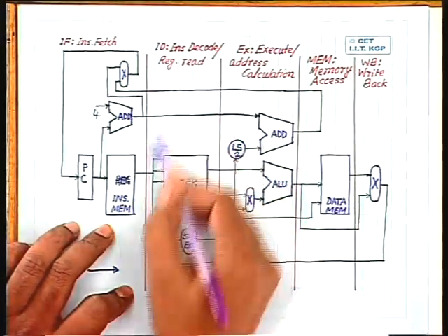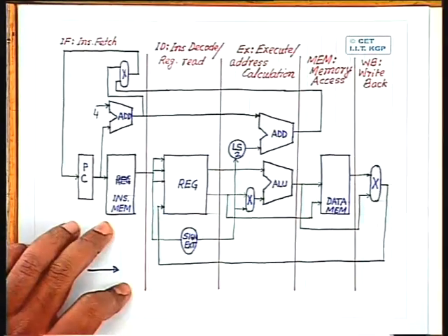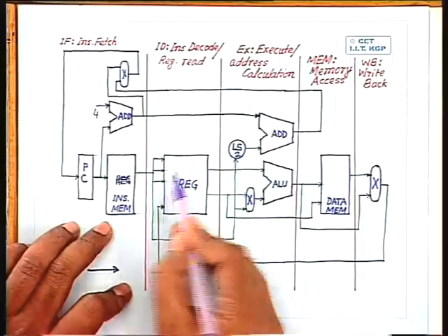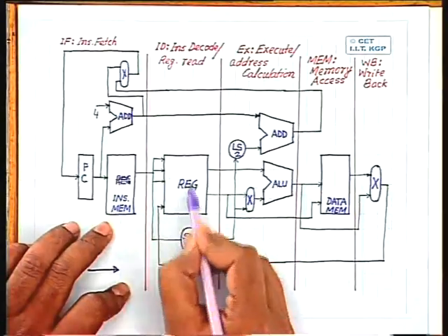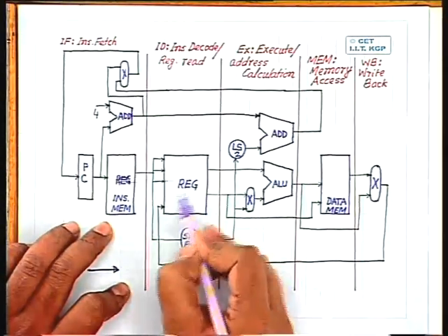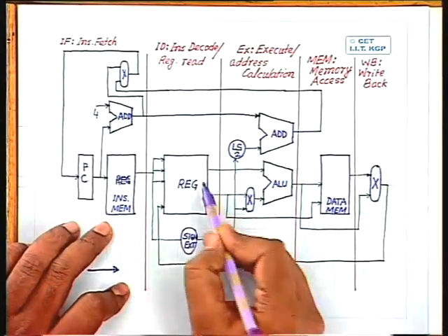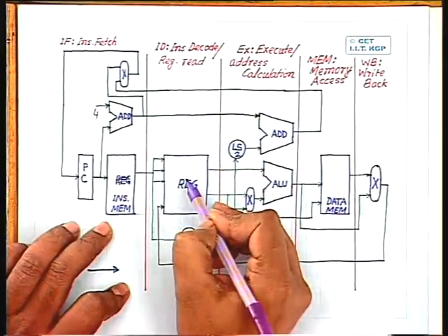In this particular case, possibly it will not lead to any problem, because the operation that you are doing in ID is only register read, and we have already said that even if you read the registers, you are not executing on them, you are not doing any performance on them. So the operation that you do even in this ID stage is not harmful.